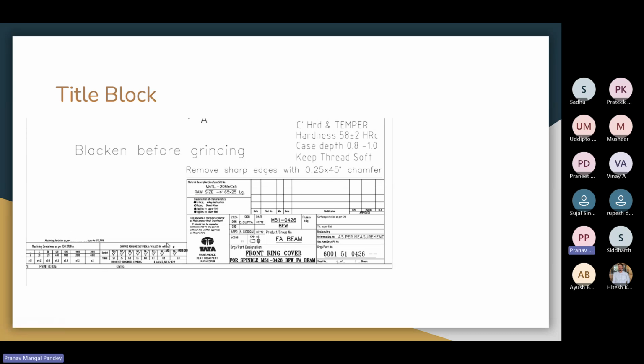This is the extended part of the title block where you talk about the surface finish and sometimes the tolerances and which standard is being used, for example the ISO international standard. The part above this doesn't come under the title block, but you can add things like notes.